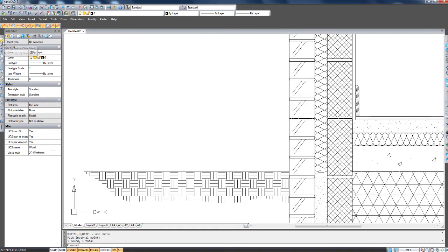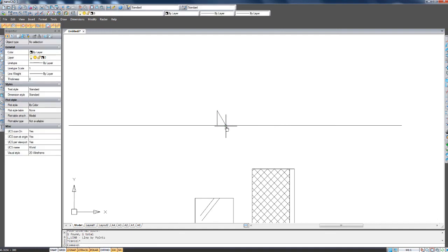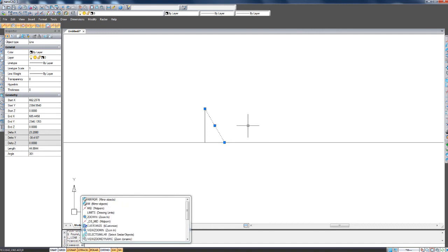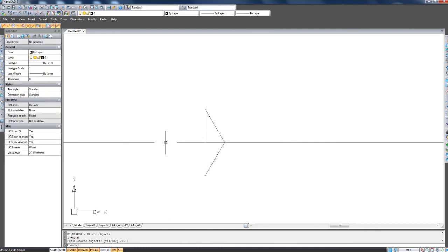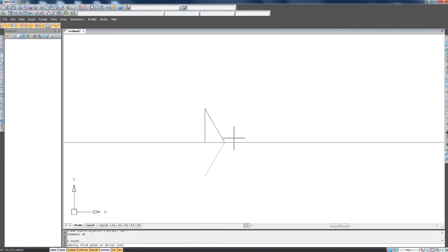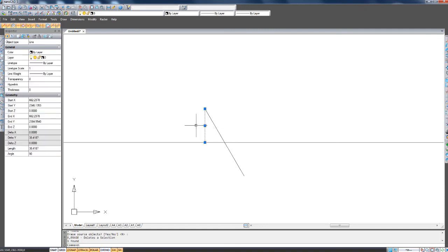And the last thing to add to this is a break line, which we're gonna have to draw from scratch. I'll draw a symbol like this, then like this, and I'll mirror this 2 times. Enter. Mirror this again. Enter. Delete this. And I'll mirror this.